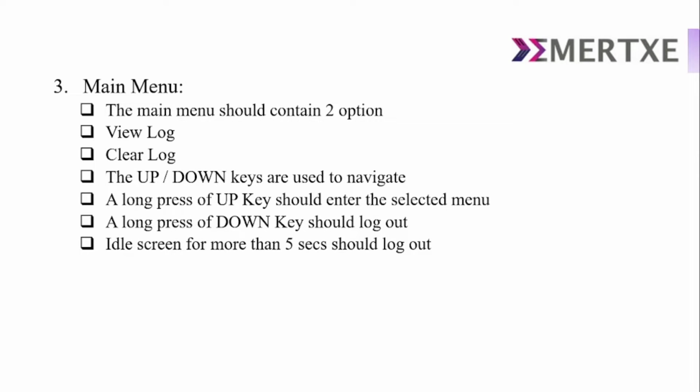For the last feature, the main menu should contain 2 options. The first option should be view log and the second clear log. The up-down key should be used to navigate the menu. A long press of the up key should enter the selected menu. A long press of the down key should log out of the system. An idle screen for more than 5 seconds should log out on its own.